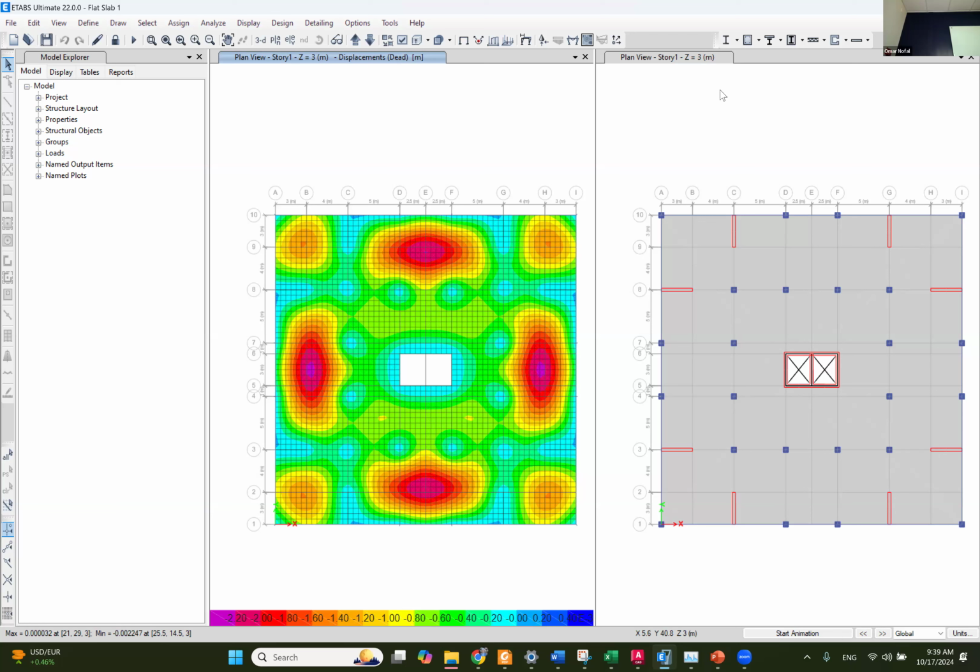So I did a 2D model. That's still a 2D. It's 1 story and it's a 2D model. And yeah, you will tell me, okay, it's a 3D. Yeah, it's a 3D, but I didn't include the total story, just 1 story alone. So I can't rely on this information. And by the way, when you run this and you run the SAP 2000 model, this one is going to get less bending moment. Why? Because it models the columns, not hinges. There are columns, okay? So the columns absorb the moment from the slab system. All right.